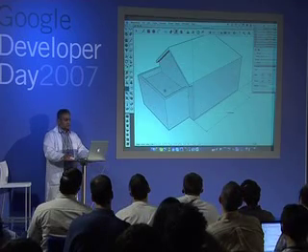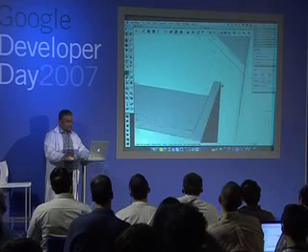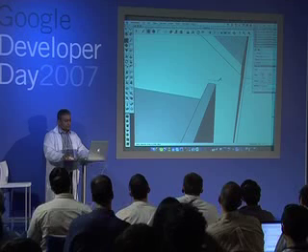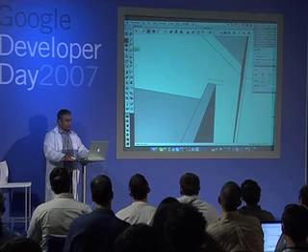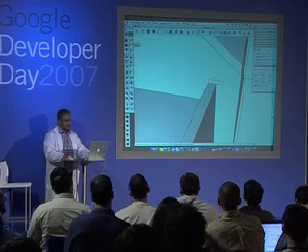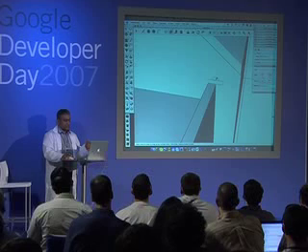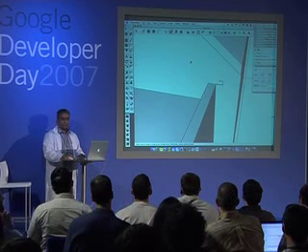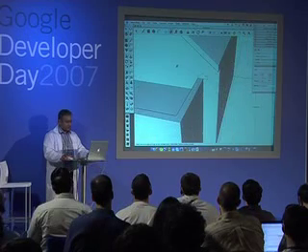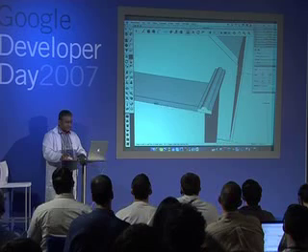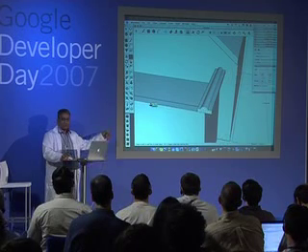Okay. Let's put some more detail into this. I'm going to put a cover, coping cover on this wall. So I will draw a shape. I will put some curves into this because I can do that with SketchUp. I'm using my rubber tool. It's just like rubbing on a piece of paper. I don't need that. Okay, I could select it all. Okay, so I have that tool. I can use my push-pull tool and I can pull that, but I need to go that way as well on top of that wall.